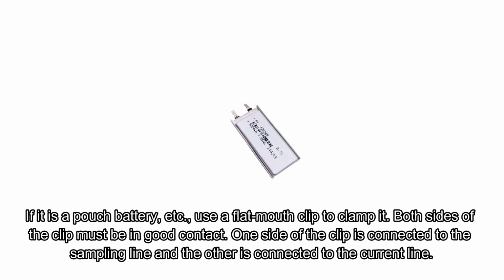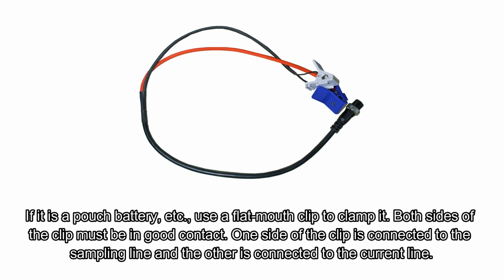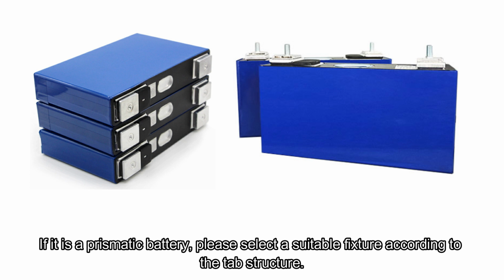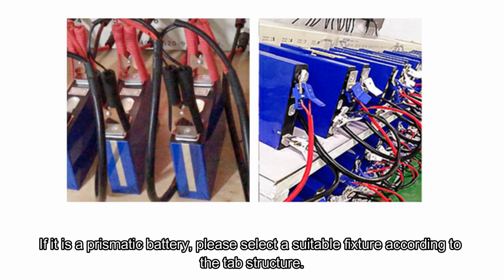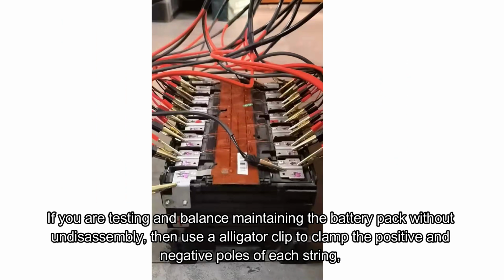If it is a pouch battery, use a flat mouth clip to clamp it. Both sides of the clip must be in good contact. One side of the clip is connected to the sampling line, and the other is connected to the current line. If it is a prismatic battery, please select a suitable fixture according to the tab structure. If you are testing and balance maintaining the battery pack without disassembly, then use an alligator clip to clamp the positive and negative poles of each string.